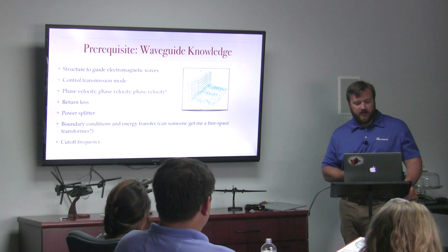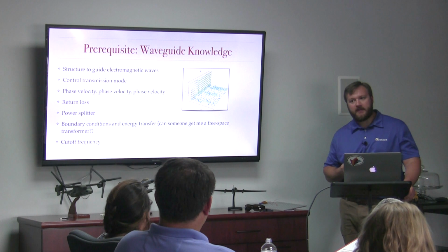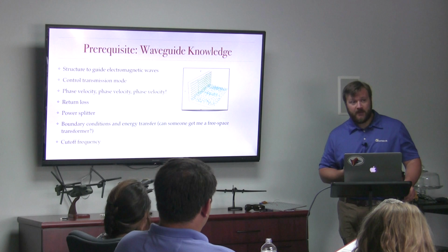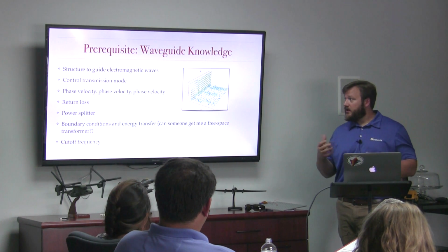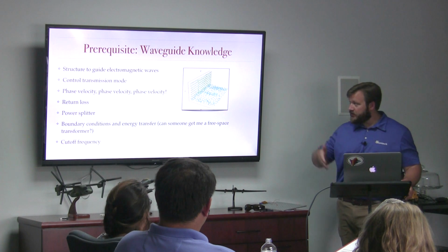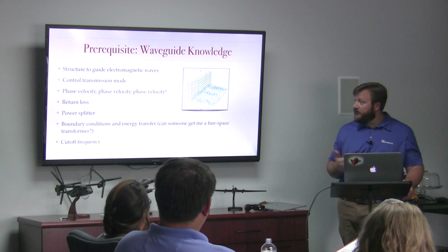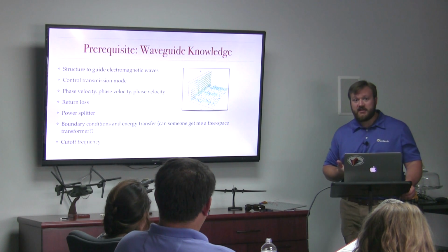All right. Something we're also doing is we're actually changing the speed of propagation of the energy going down the guide. Now, when we send energy down the guide, we can deal with multiple modes in the electric field and the magnetic field that's coming down the waveguide. So for this, we're using a TE10. Our dominant mode in the waveguide is TE10.